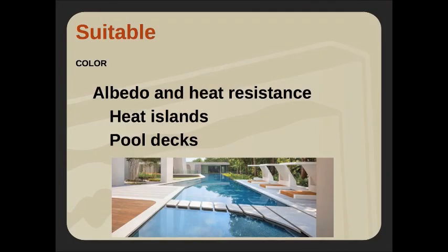Another thing to consider is if we're doing this in pool areas, exterior, what's the albedo and the heat resistance of the material? A granite on a pool deck is going to get really hot. Whereas if we get a light colored limestone or a light colored travertine that we've done all the other homework on and know it's appropriate for this use, those aren't going to retain as much heat. So the bare feet aren't going to suffer as much. So again, it's function over fashion, as they say, in this particular case.